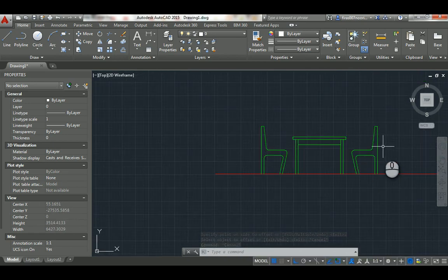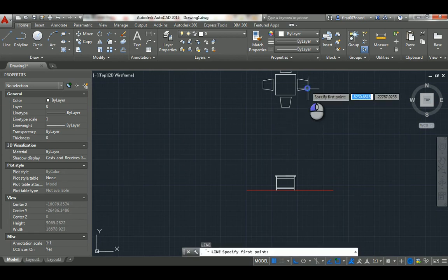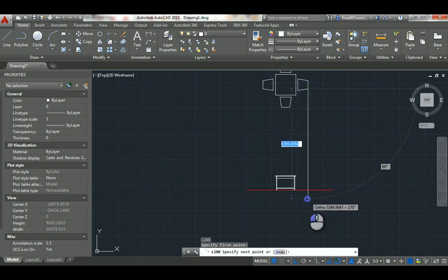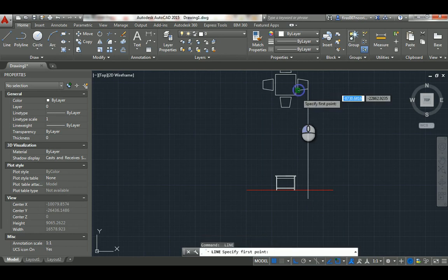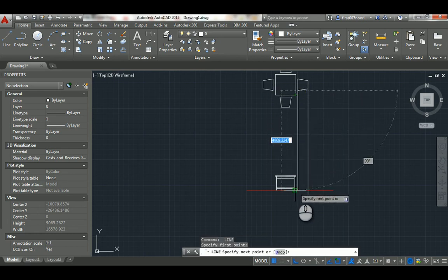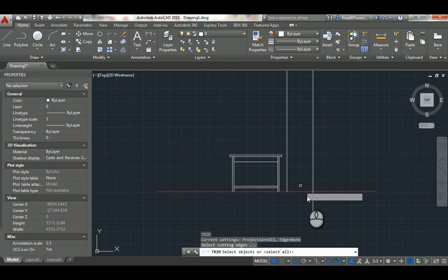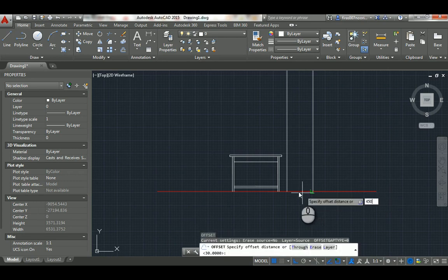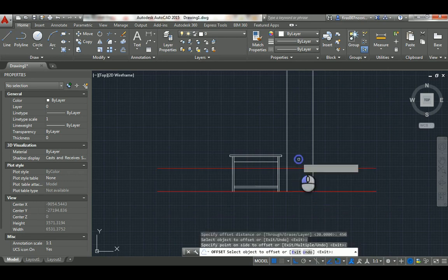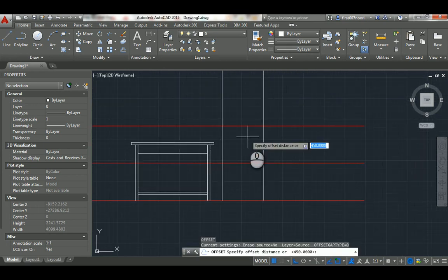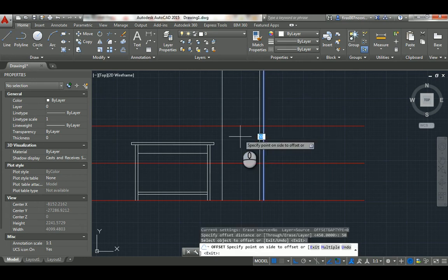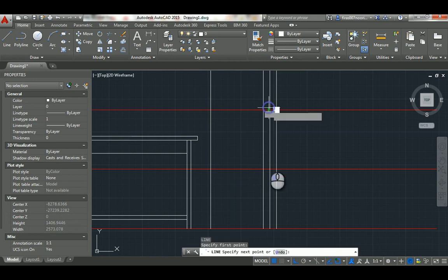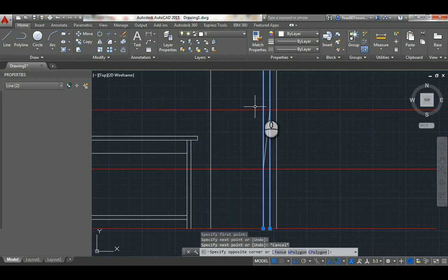And chairs, same. I'm just going to take those lines here. There are so many different types of chair design you can do. Anyway, I'm going to have 450, about the standard for the sitting area, another 450 for the back of the chair, and then let's say 50 maybe, and maybe another 50. Just connect the line from here to here, and probably we need to get rid of those.